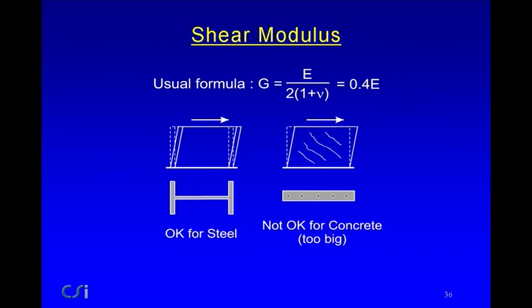That's mainly because the effect tends to be like a frictional effect, and it's actually extraordinarily difficult to get it to work reliably when you have friction. Friction is very complicated. So in the present inelastic shear material in Perform, you have to take into account the axial force at the time you specify the shear strength. Perform will not automatically vary the shear strength for you based on the axial force.